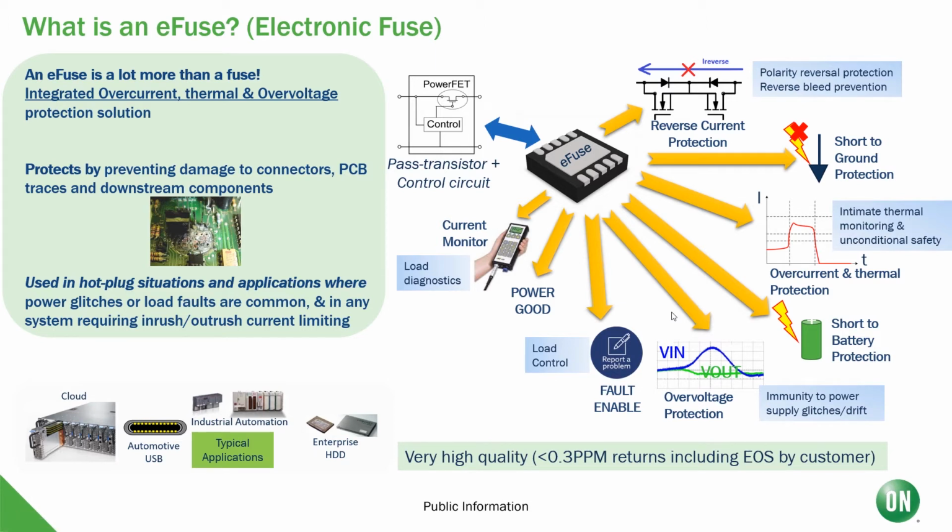So, what is an eFuse? An eFuse is not just an overcurrent protection solution, it also solves your thermal and overvoltage protection requirements, as well as short-to-ground and short-to-battery protection. In some cases, such as solid-state drives, reverse current blocking is also required to prevent large capacitors from bleeding charge upstream during a shutdown event.